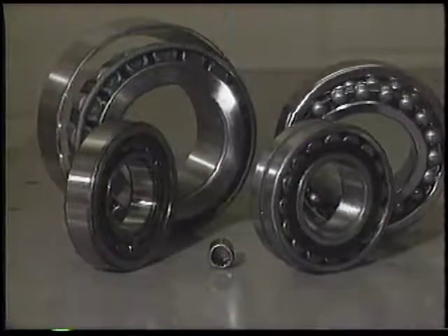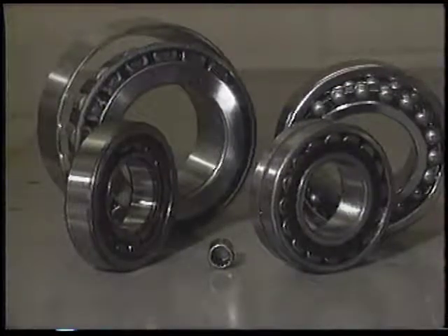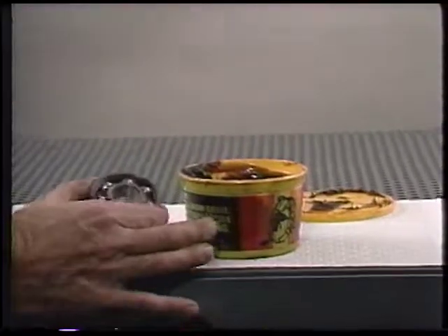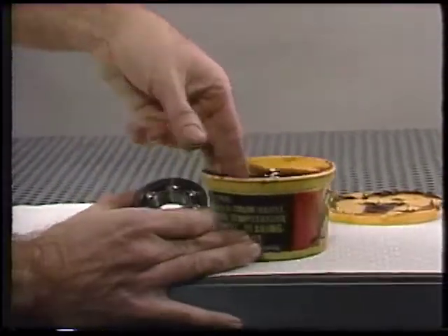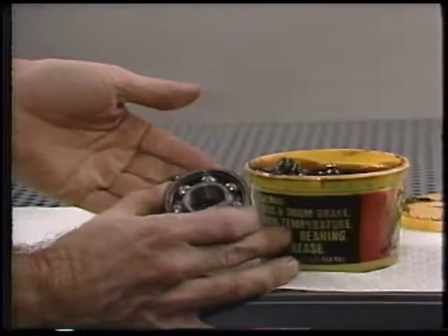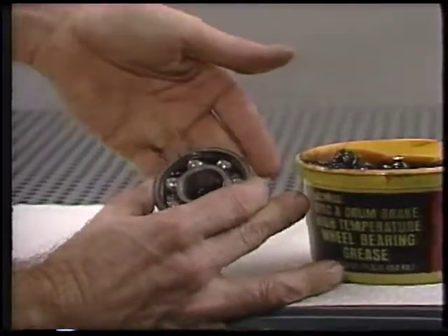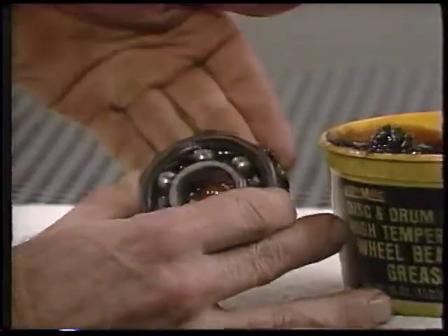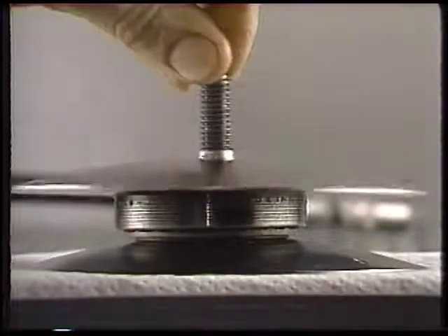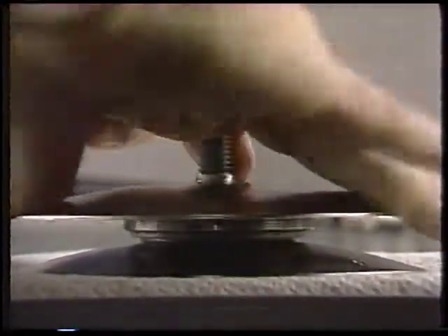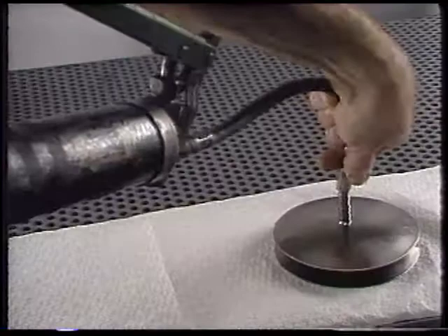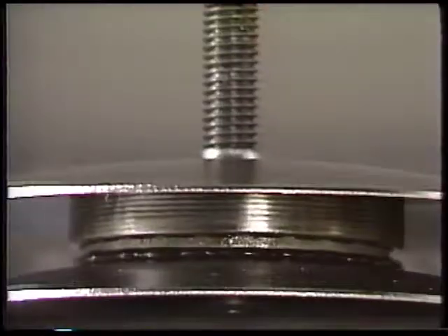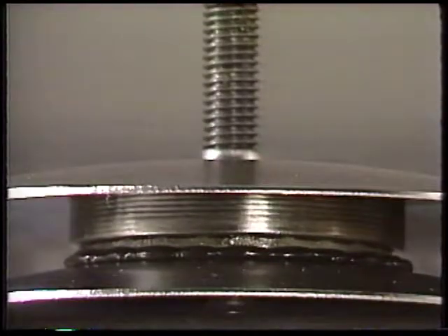Rolling element bearings may also require lubrication at the time of installation. When this is done, it must be done correctly. Cleanliness is essential. Hands, tools, clothes, and the work surface must be absolutely clean. New, fresh grease must be pushed completely through the bearing from one side to the other in order to coat all parts. This can be done by hand, but it is preferable to use a tool to pack the bearing. If the bearing is filled with new grease, make sure there is some way for any excess to be expelled during operation. Excess grease may make a bearing run hot and could blow out the seals.